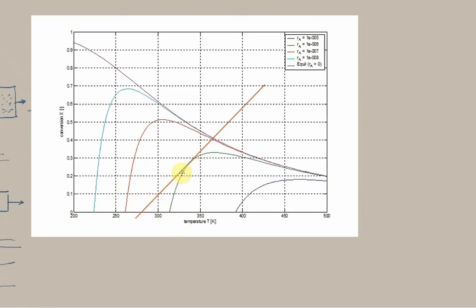So moving down here is a reduction in the reaction rate. Moving up here also is a reduction in the reaction rate. So going up here, we are moving closer and closer to that red line, and so the reaction rate is going down there. So clearly, the highest reaction rate along this line is at this point right here. So where this line is a tangent to this green line, we have the maximum reaction rate. So let's mark that as a useful point to know about, right?